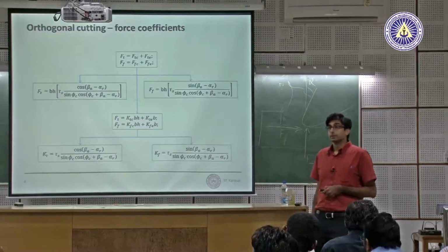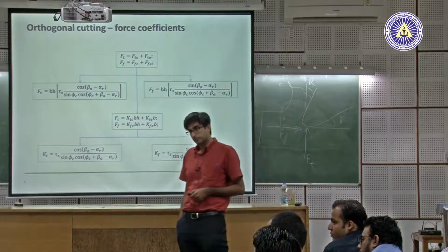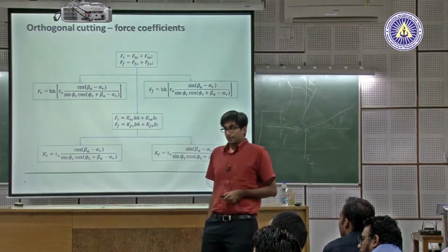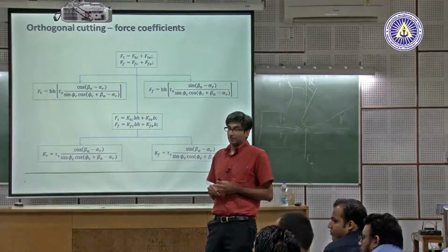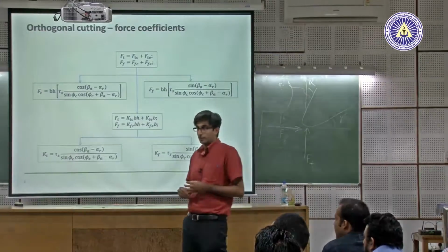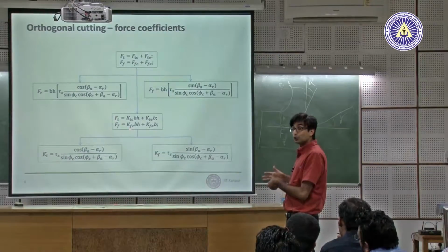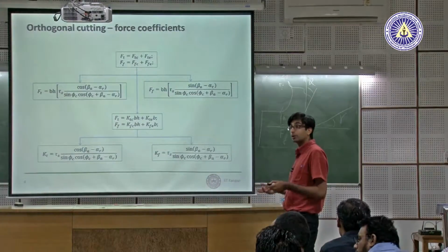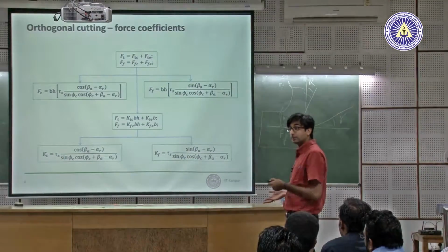The cutting force constants, they are proportional to your radius. Ploughing action is a factor. Yes, to a certain extent. So it incorporates that. But we don't have coefficients here for that. There is no closed form solution for the edge coefficients, because orthogonal cutting assumes a sharp edge. These edge coefficients are absent.